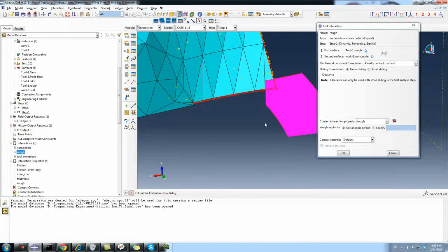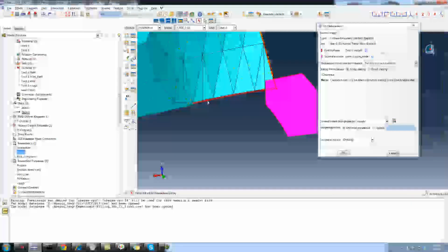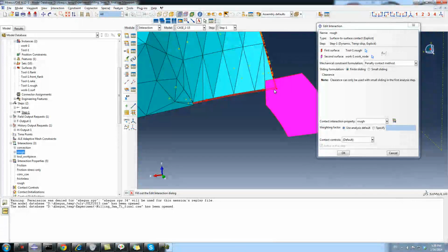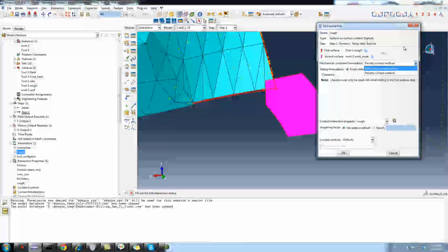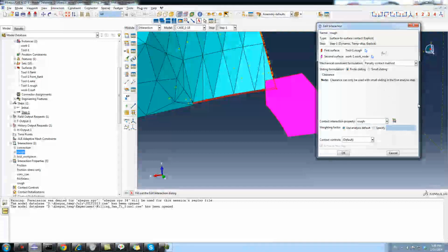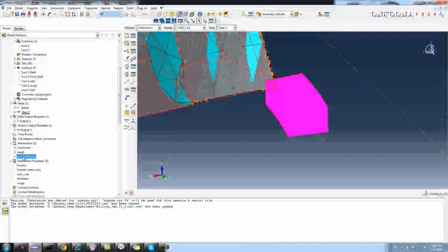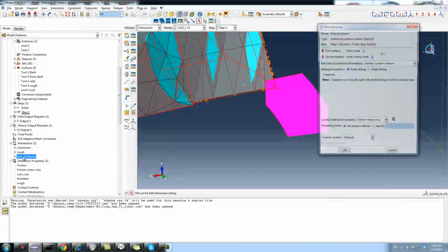If I want more precise friction, I can just give it as a boundary condition. Friction is this one and this one and this one. Give it some, what's that? Penalty friction. Yeah, penalty, and your kinetic, whatever you want. And then friction this one. Okay, this is defined here. Tool, workpiece, two workpiece. So this is also the friction.